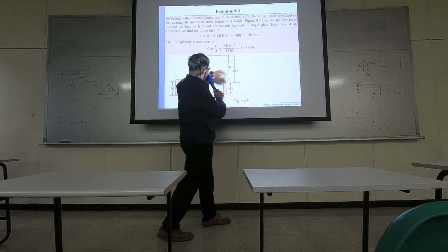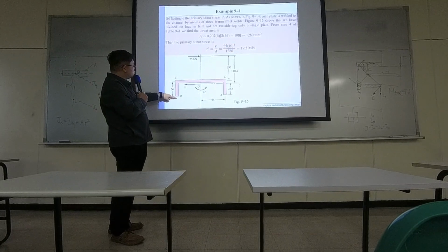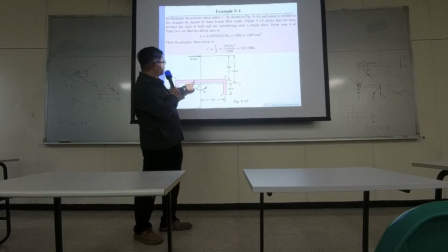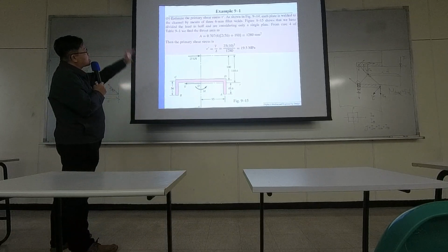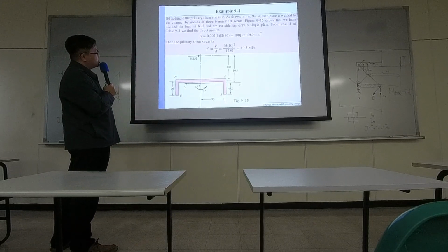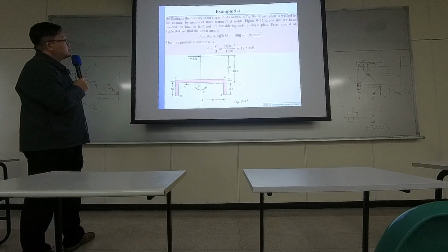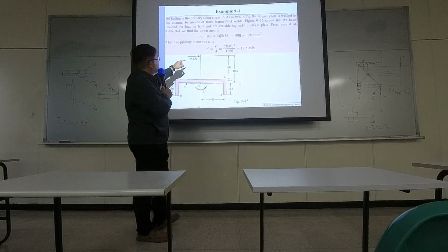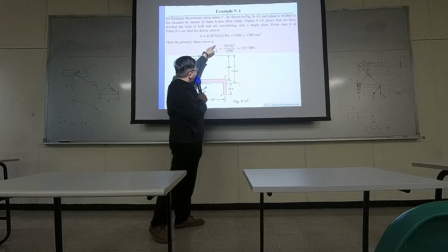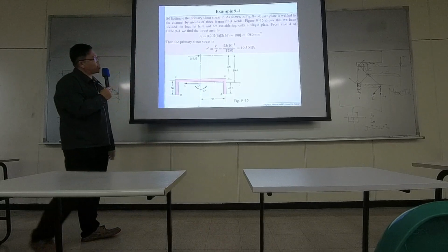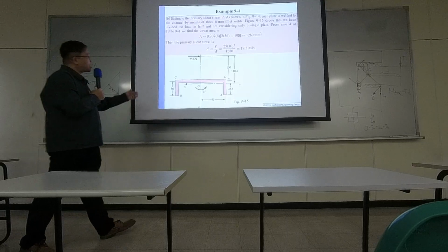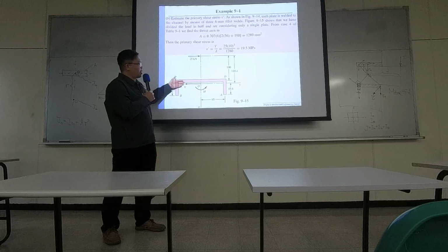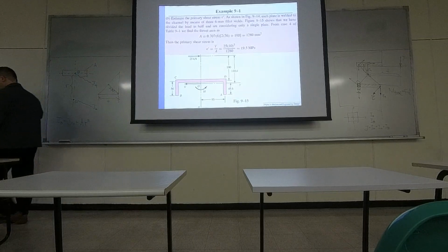Now these are just computing the length. So 2 times 56, for both sides, and then 190 for the top. So that's the total area of this C shape. And the normal stress basically is going to be the shearing force, the force over area. That's how you can compute the shearing stress. So there will be shearing stress going horizontally everywhere inside this C shape.